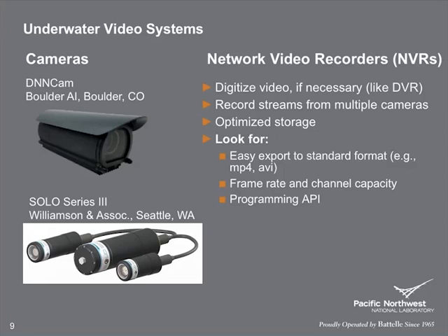Pay attention to their rated frame rate and channel capacity. And then as a bonus, some of these NVRs offer a programming API, which means you can write scripts to control the recording, to extract the video, and integrate that with other software that you may be using to do the automated analysis. So that's a really nice thing if you can look for that feature.